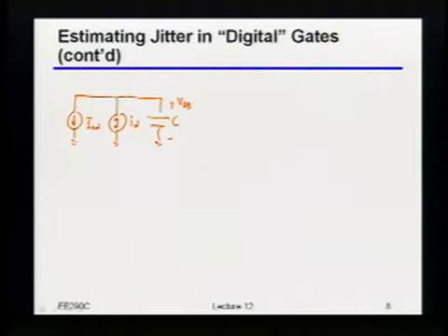What sets the delay in the first place? What's the nominal waveform you should get at the output over here? So if I looked at, this is of course V out. If I looked at V out versus time, what should that waveform be doing once the current turns on? Ramp down. Yeah, it should be ramping down, right?